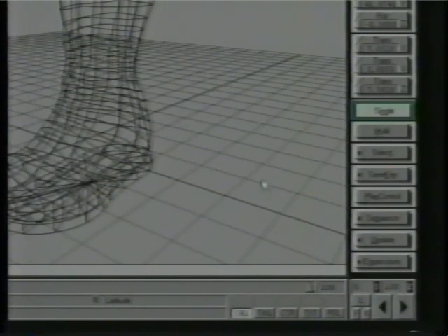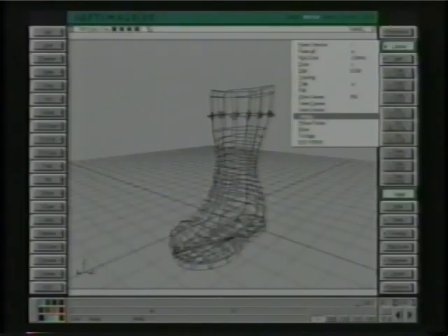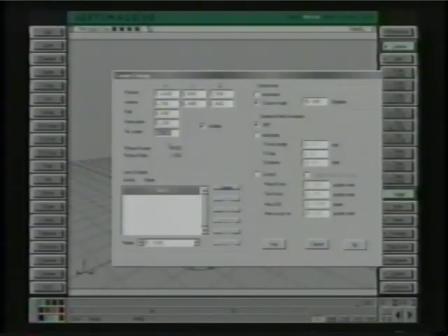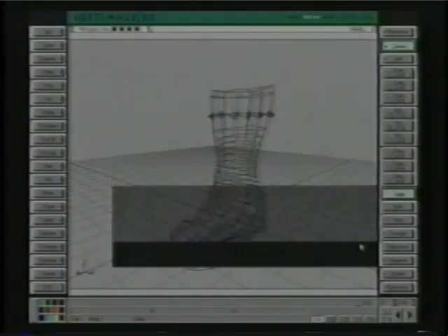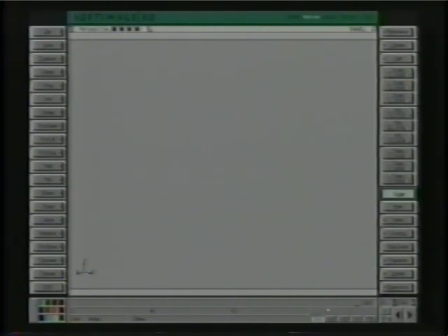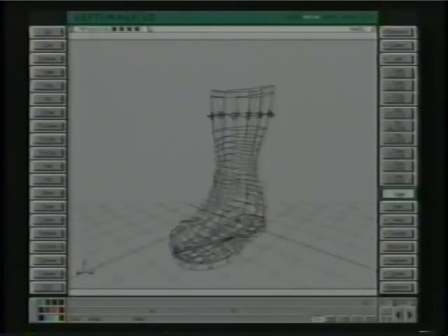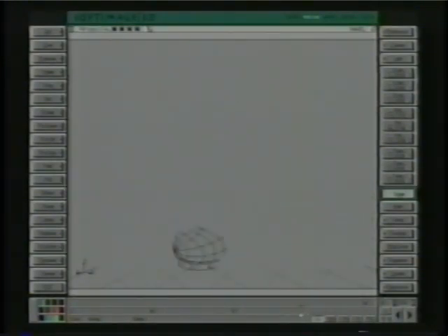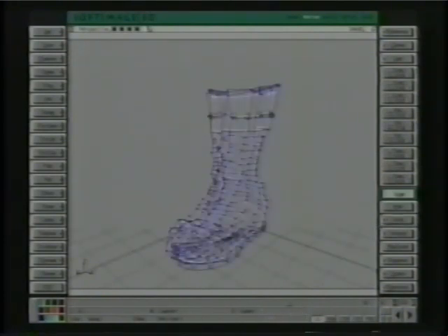Slide to the last frame, frame 100. Now save another keyframe with the far plane right in our face, something like 1. Save key, camera, far again. Now, if you just drag the timeline, you get this very handy virtual slider. You can quickly position it without even changing objects. So if I slide this way back, it gets lost in the fog, no problem. You can just slide that back and see it.